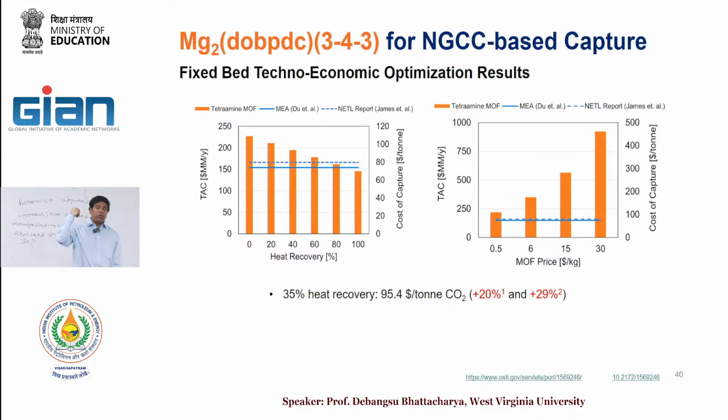So the typical moving bed regime is where you have the minimum fluidization velocity. Generally, it is kept at about 2 to 3 times that. When you go to the bubbling fluidized bed, it goes to about 10 to 12 times. In the circulating fluidized bed regime, it can go up to 20 to 30 times. That is where the trouble comes. So up to about 2 to 3 times the minimum fluidization, most cases, of course, there is some attrition resistance expected, but the particle-particle collision is not that prominent in this moving bed regime.